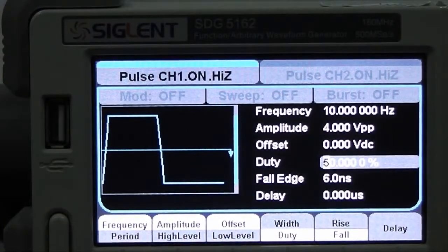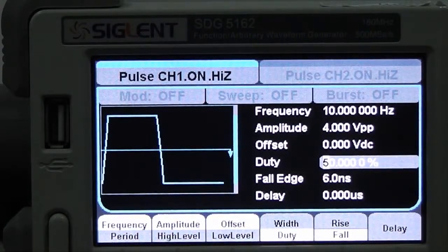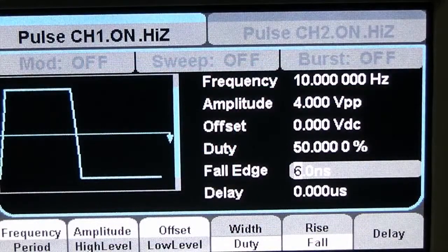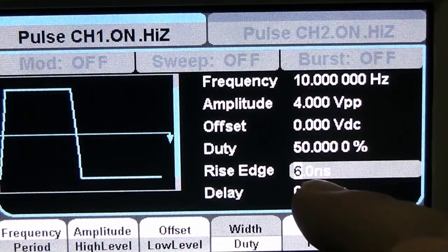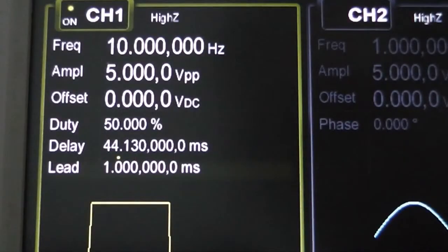While outputting a low frequency pulse, EasyPulse provides a rapid rising edge and trailing edge versus an ordinary DDS pulse edge, which is very slow, in the microsecond range. The edge of the EasyPulse wave can be adjusted over a larger range. When generating a 10 Hz pulse waveform, the minimum falling edge can be set as low as 6 nanoseconds. But an ordinary function generator cannot achieve transition times this fast on either the rising or falling edge.